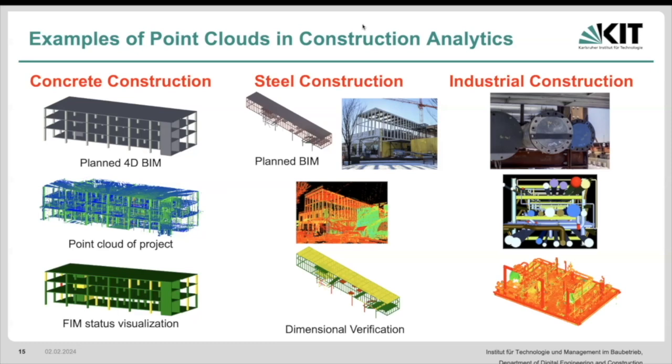When it's going to be shipped to site in, let's say, minus 30 degrees in Canada, we need to know that these locations of these flanges, where these pipes are going to be joined, are going to be in the proper location. How can we guarantee that? We need to be able to get the point cloud, extract the information that we want from it prior to it going to site, and verify that.